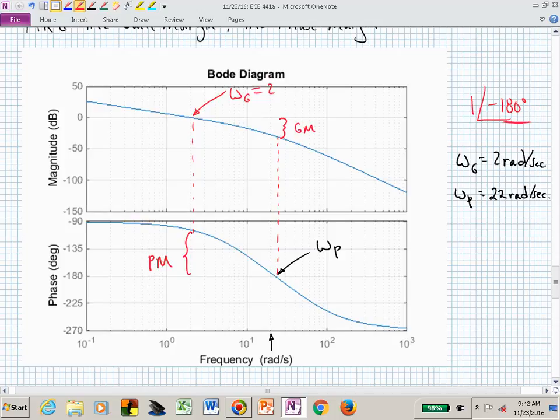And now maybe you struggle with this, but you have to eyeball it on the exam. You just have to sort of say, how much are these values? How much can you change your phase before you reach -180? Well, in this case, your phase margin can be reduced as much as, well, it's not quite 90 degrees because you're below -90.